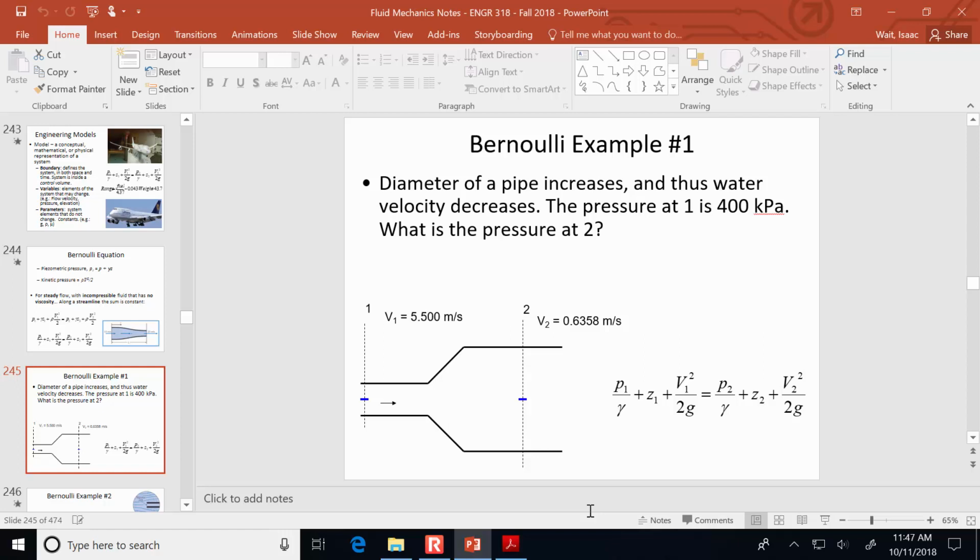It's because we only applied Bernoulli's equation at a couple of points that are relatively close together, because Bernoulli's equation can't handle pipe friction. But in a situation where there is pipe friction, then there's going to be pressure decreasing in the direction of flow, and that's going to determine whether flow is going to the right or to the left: the pipe friction and where the energy is higher.